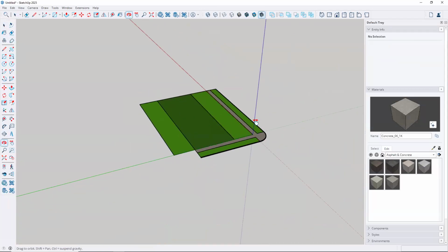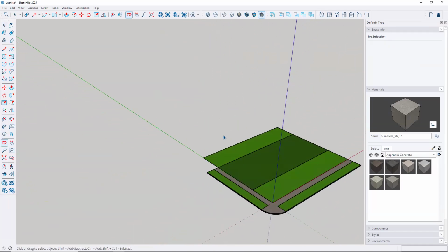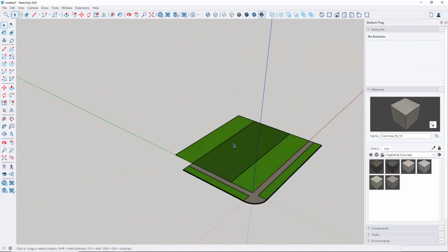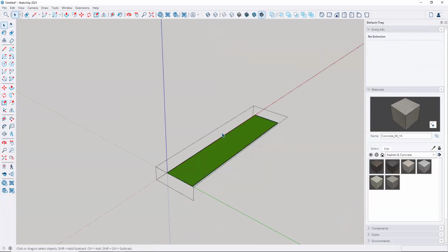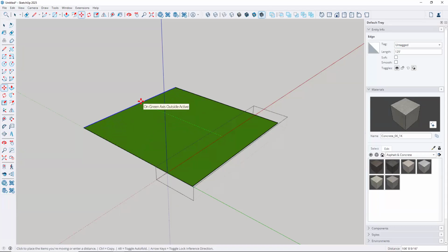And then I do want the property to keep extending over. I want to show at least another 10 properties. The city block is pretty long. So one thing I could do is take this group here, double click it, take this edge right here, have it selected, type M, and just move that over and keep going by increments of 25 feet. So it could be another 50, another 75, another 100, and so on. I could do that. Easy enough to do.